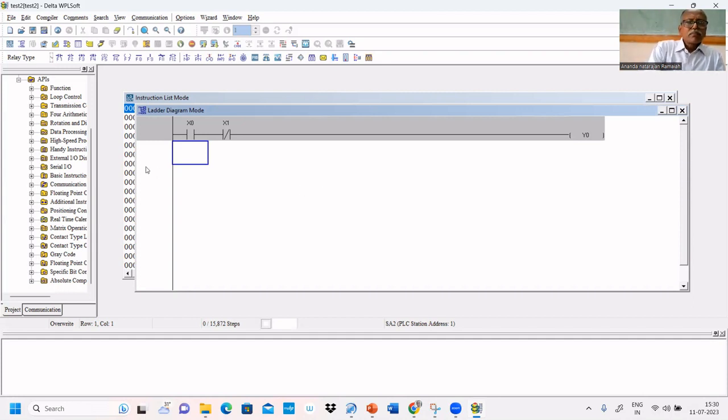Second part, second rung. The first line is called a rung. First rung is over. Second rung we have to draw. Second rung, X0 bar, normally closed contact with the same name. Already I told you that X0 is in my image table. It is a memory.